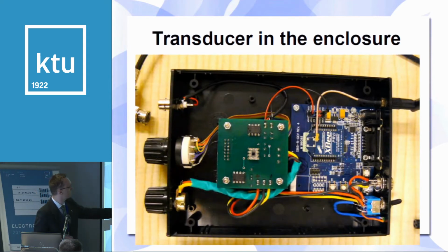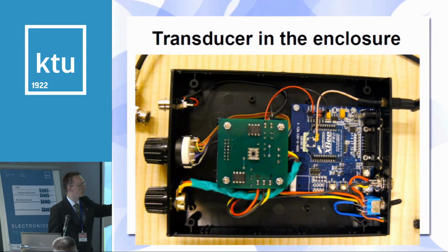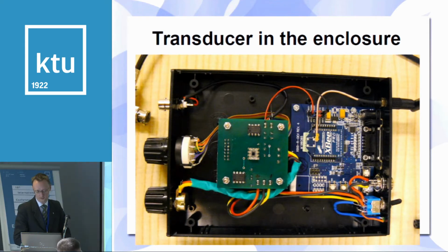The green board in the middle was what I constructed, with the OPT101 in the middle, some components on the other side, of course SMT included, and knobs to change gain and to change reference level. The board is attached to an XBee development board, which samples the value and transfers it to PC.